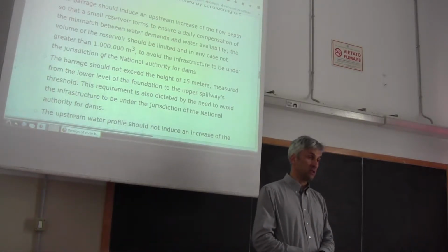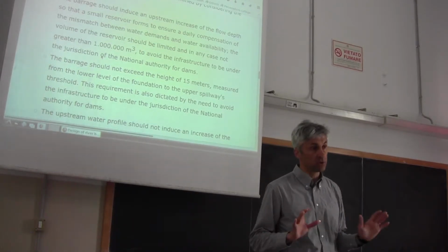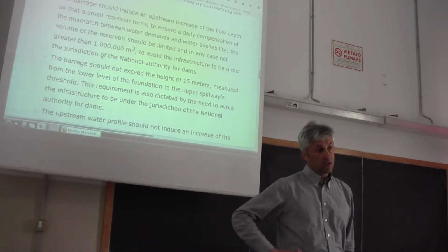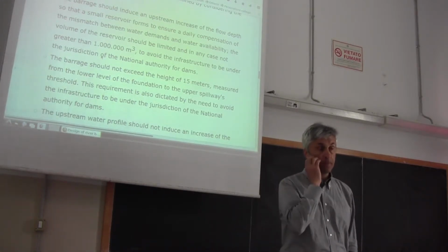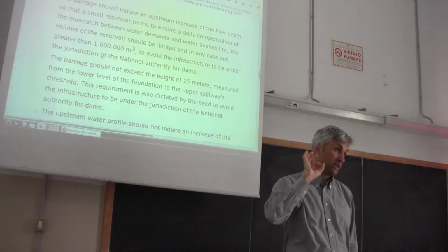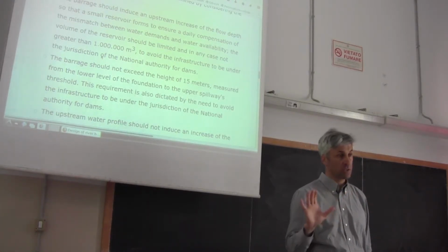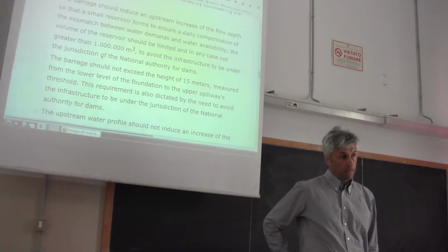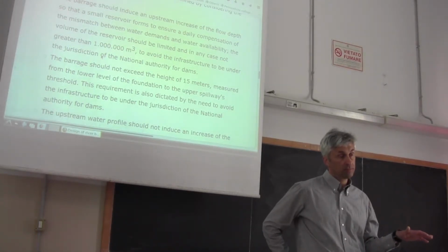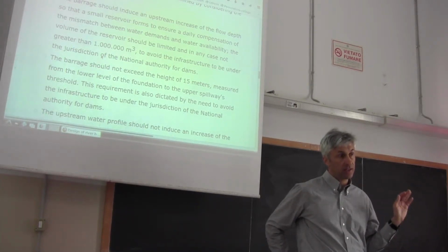So after we gave priority to the environmental flow spillway, the next priority is for the diversion spillway. And what is the constraint that you have to impose here? The constraint is that you don't divert any water as long as you don't release the environmental flow downstream. So you don't take any water if you don't deliver the required environmental flow downstream. So you start releasing the environmental flow. When environmental flow is released, then you can start taking water.